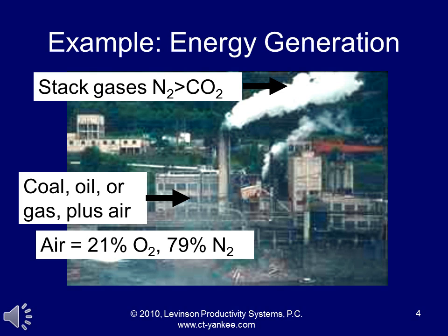Now, the fact that the nitrogen does this is a theoretical argument for burning the fuel with pure oxygen. On a practical level, the cost of the oxygen and also the cost of the equipment necessary to contain the kind of temperature that would produce could be practical obstacles, but that's the kind of thinking that the material and energy balance would lead to. Also causes one to think about fuel cells, which end up bypassing some of the thermodynamic efficiency limits on ordinary combustion.